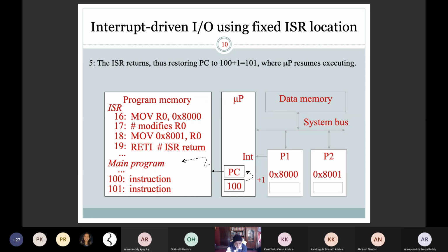So you can change the address here. It will go to one address table from which it will read the address and load it to the program counter. So this is also as good as a vector interrupt, because you can really change the address here. The address of the subroutine or ISR will come back from the table. This is called the third type of interrupt, the interrupt vector table.